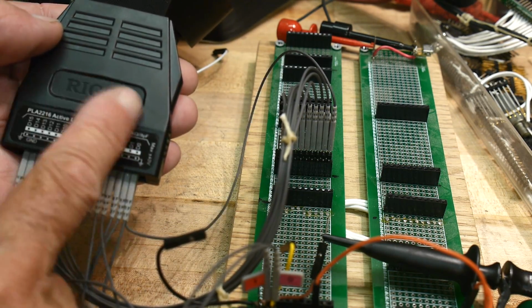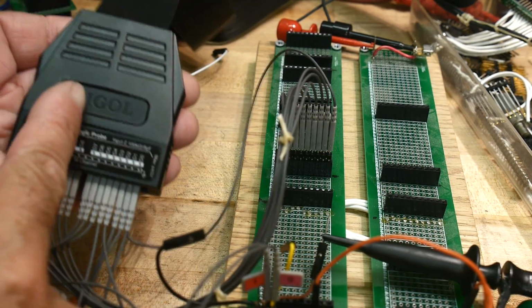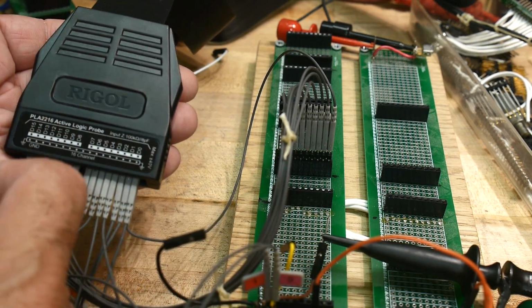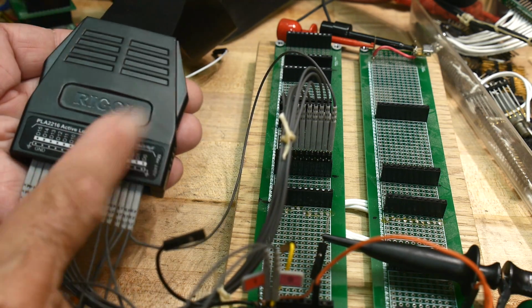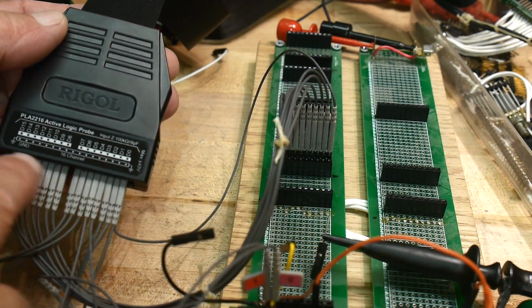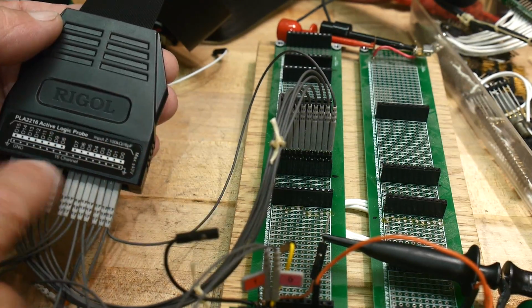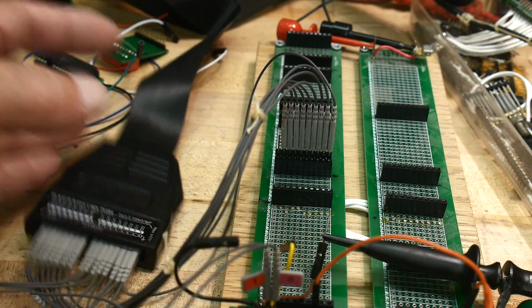It'll fire just like a logic gate. So it's like having a trigger on every single edge, and you're not just looking at waveforms, you're looking at trigger events. This is a pretty fancy probe. I have it hooked up so that the upper 8 bits are the bus, and the lower 8 bits are available to take a look at various things, okay?